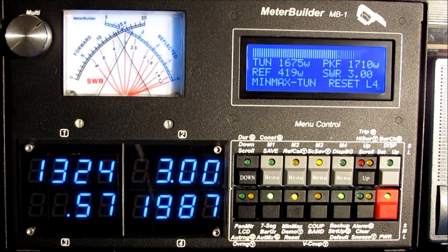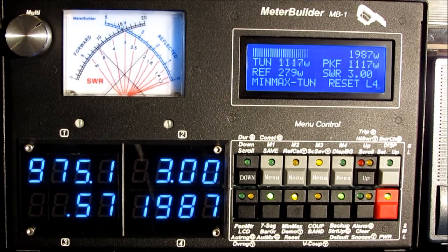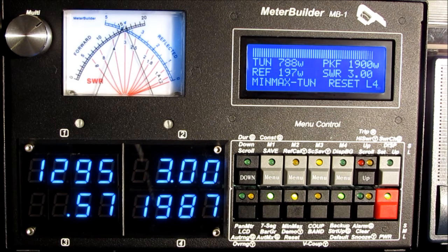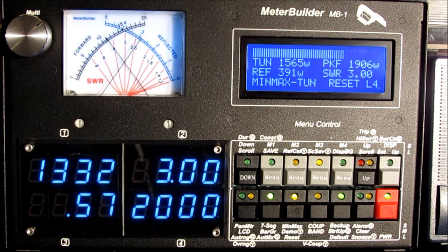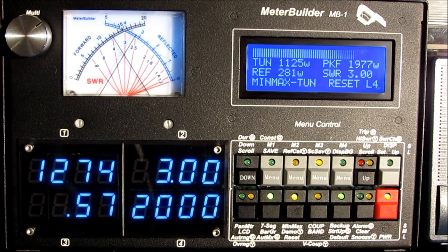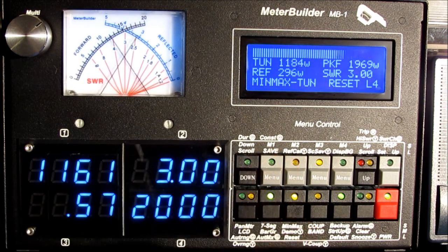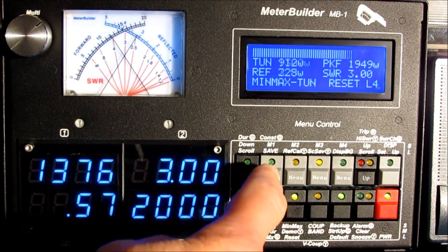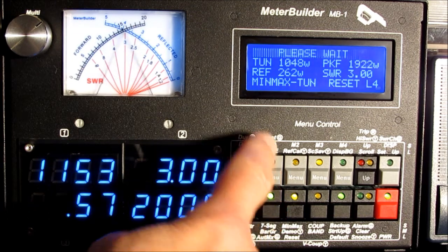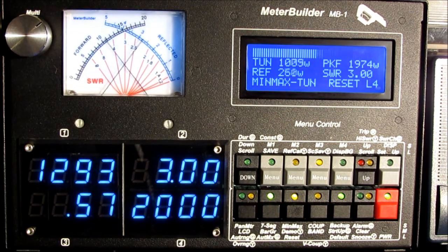Now, we spent a little bit of time setting the meter up, and you don't want to have to go through this each time you power up the meter. MB-1 has 7 configuration sets where you can save the 100+ parameters that are part of the settings of MB-1. If I want to save these settings to the startup set so that they're restored every time the meter is powered up, I've got a save legend in my silk screen there. Simply give this a long press. I see a confirmation message that the settings were saved to the startup set.